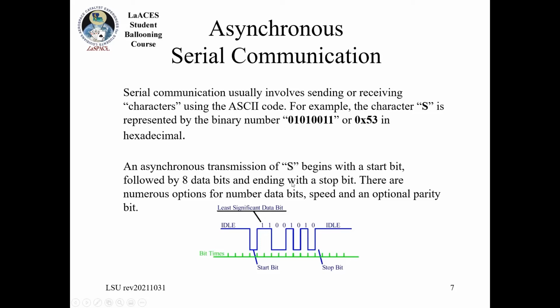So like I said, you start with the start bit, you send your 8 bits, and then you have an ending signal here. And in this particular case, you can see that when the line is idle, it's up. So I always have to pull this data line low, pulse it briefly low, so that the other device knows to start counting and that I'm going to send something.